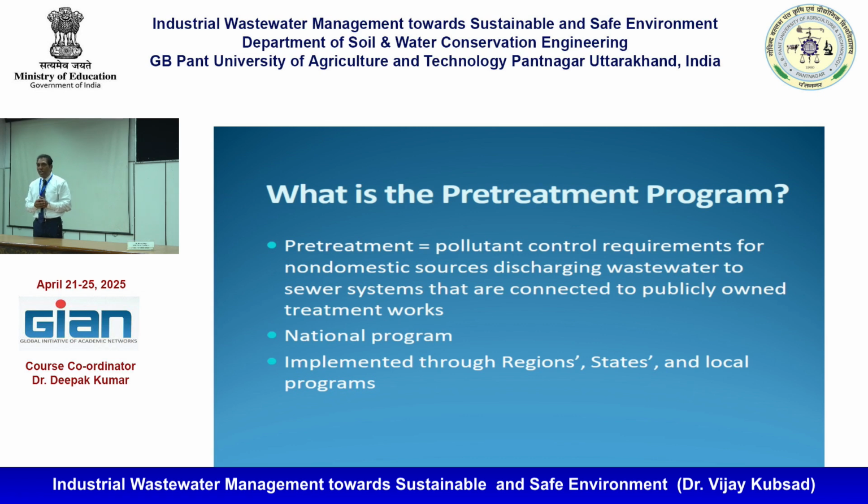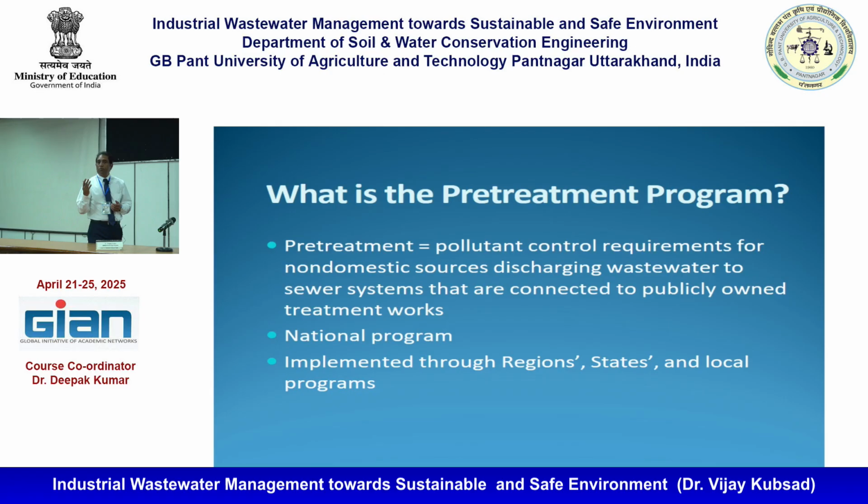For example, if I say the federal BOD limit is about 60, just a number, then locals say, no, our treatment plant is small, we can't accept 60 BOD, we will accept only 30. Then you have to treat that BOD and dilute it for residential and industrial. So that is how the question comes.